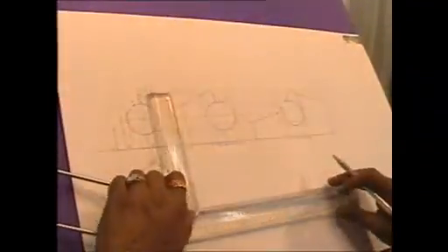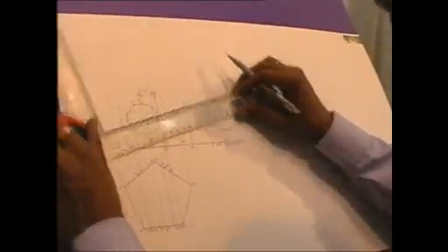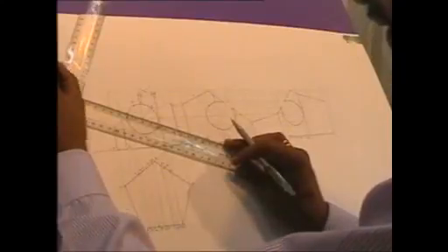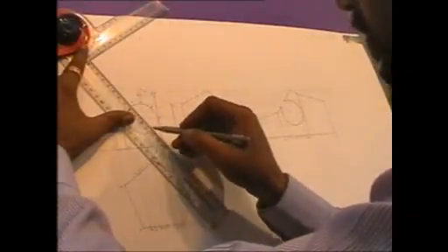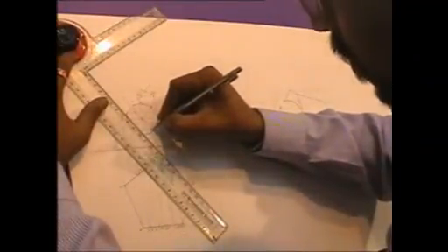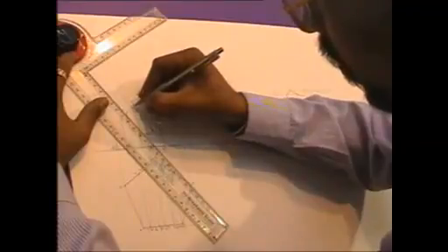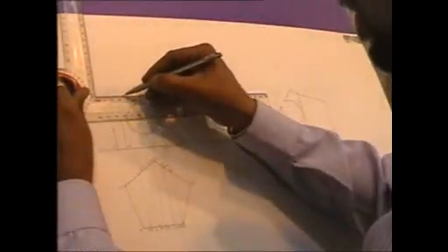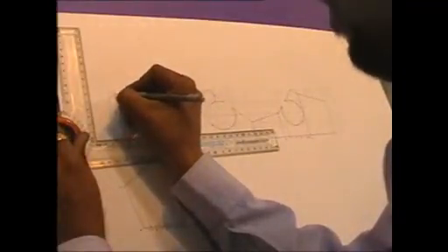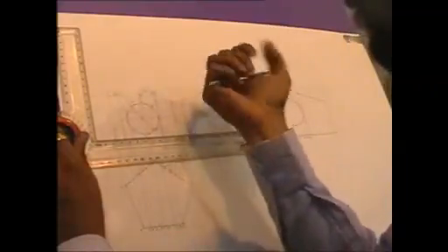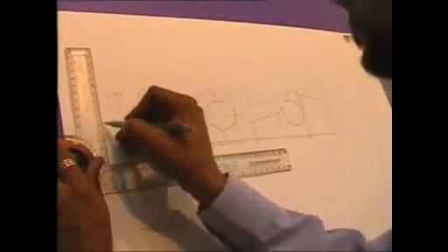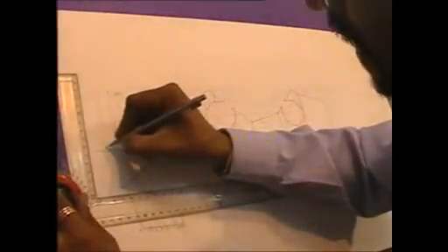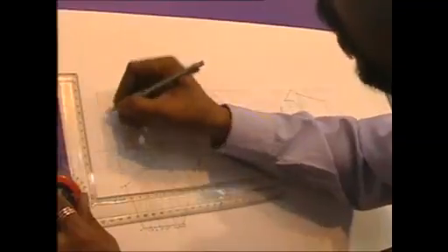Diameter of the circle can also be shown using some line. So I am taking some line over here and will be showing the diameter of that circular hole. So the diameter of the circular hole can be shown. It is phi 40. The height of the prism, which was given to us as 75, even that can be shown. These are all the dimensions which I am showing in the front view.